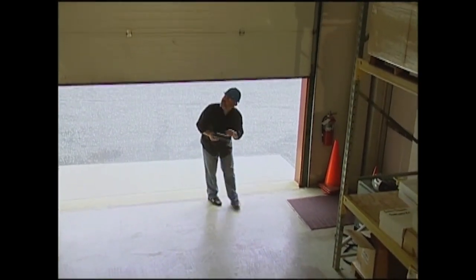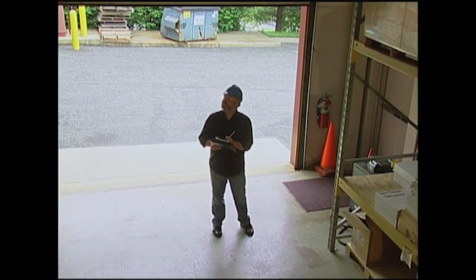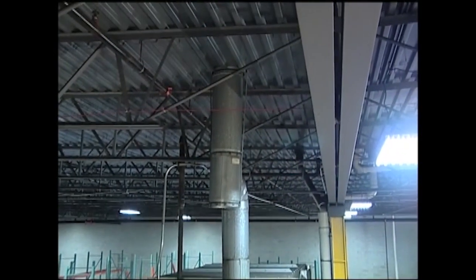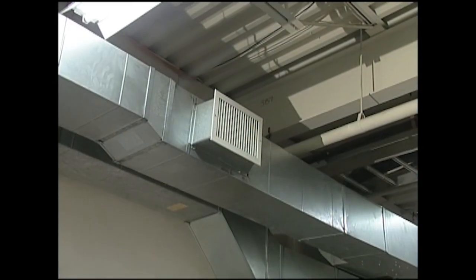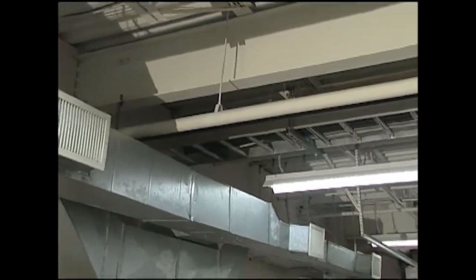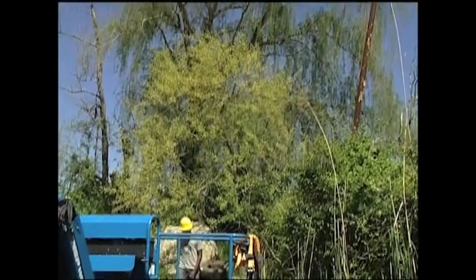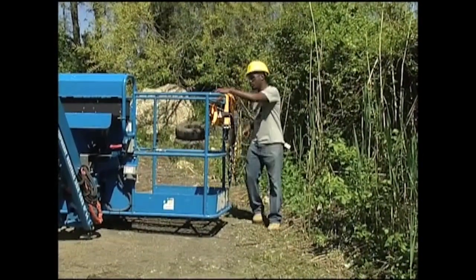Your surroundings can also be hazardous when you're operating an aerial lift. Overhead hazards can be especially troublesome. If you're working indoors, you need to be aware of beams, rafters, and ceiling heights. Keep your eye out for HVAC ducts, piping, and cable raceways as well. If you're outdoors, you want to pay attention to trees and light poles. Stay a minimum of 10 feet away from any of these hazards.